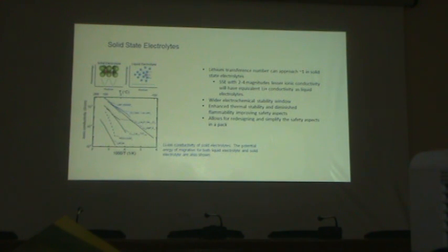Now, what is good about this is, when you have a liquid electrolyte which has a very high conductivity value, but let's say half the transport number, and you use a solid electrolyte which has a much lower total conductivity but a very high transfer number for the ion we are interested in, the cation, then even lower conductivities of ions in these materials would help.